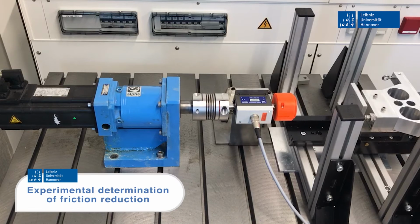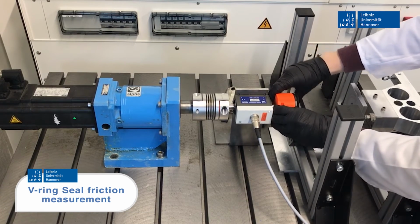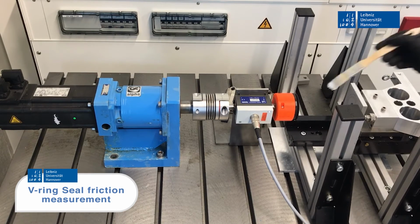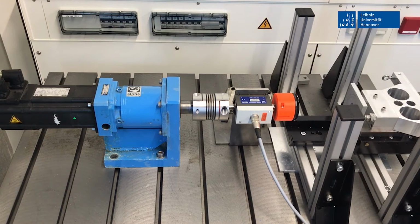First, the V-ring seal to be tested is mounted on the specimen holder of the test rig. Both the seal and the counter surface are lubricated with the help of a brush. The fitted width, which determines the contact pressure between the seal and the counter surface, is adapted to the operating condition to be investigated.